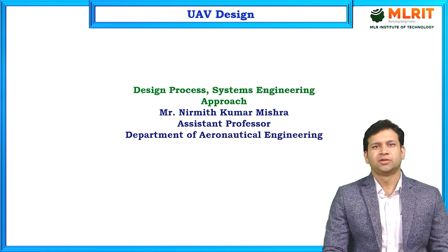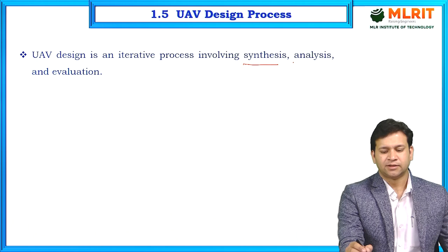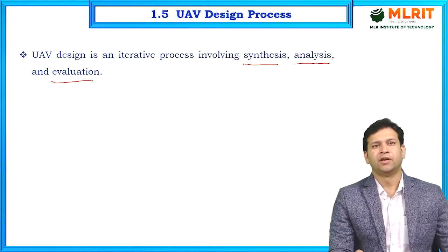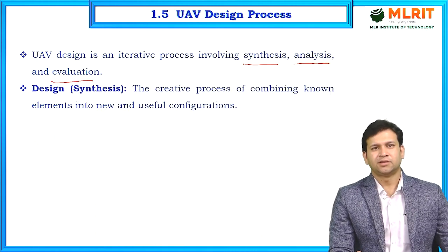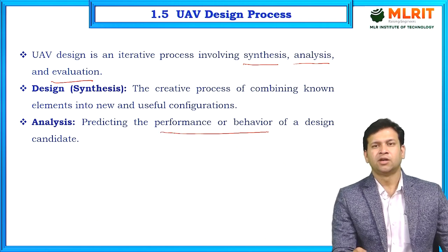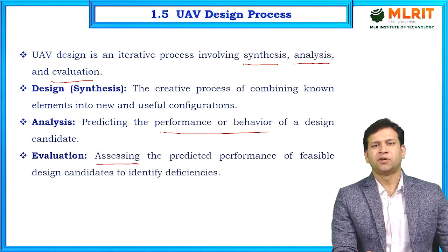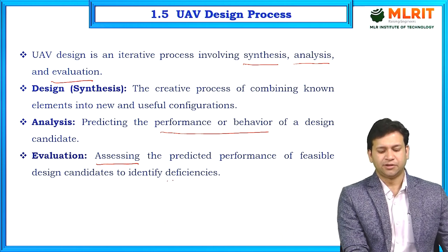In today's lecture, we are going to see about the design process of unmanned air vehicles and the systems engineering approach to build a UAV. UAV design is an iterative process involving synthesis, analysis and evaluation. Synthesis is the creative process of combining known elements into new and useful configurations. Analysis is predicting the performance or behavior of a design. Evaluation is assessing the predicted performance of feasible design candidates to identify the deficiencies.